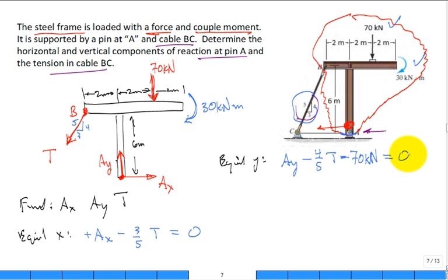Well, where's my origin? You don't have to always do it at the origin. You can do the sum of the moments around a judicious point. Now, if you've done it a few times, you'll look at this equation and say, I have unknown, unknown. Too bad I don't have one equation with one unknown. That's my preferred. But I have two unknowns in that equation. When you really get good at it, the sum of the moments will allow you to knock out two unknowns, and you'll only have one unknown in one equation from the sum of the moments.